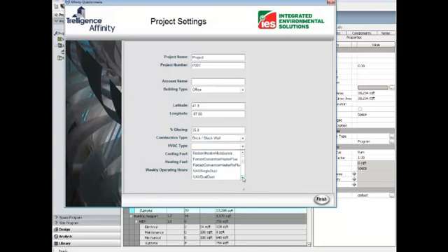Note that these selections can be changed at any time throughout the project, and most likely will be after we run the VE analyses. Once we gather temperature data, for instance, we may want to change the construction type. We will also be able to add more requirements like insulation thickness later in the project. For now, let's choose the electricity for the cooling fuel and natural gas for the heating fuel.